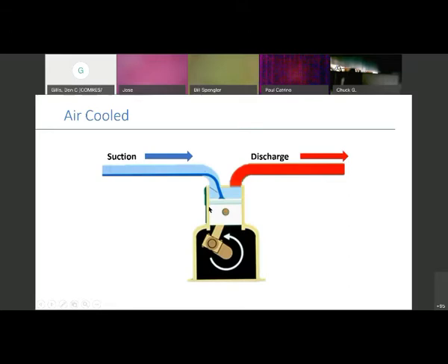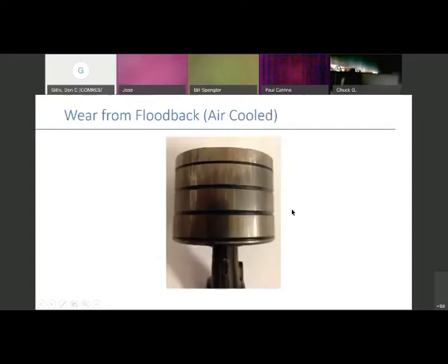On that note, this is the thinnest film of oil in the whole of this type of compressor, any piston compressor, right between that piston and that cylinder. And then we have the discharge gas obviously coming outside. Something you're going to see if you tore that down is like a thumbprint, if you will. I always use that term when we're getting these students ready for day 3, and we call it a thumbprint.